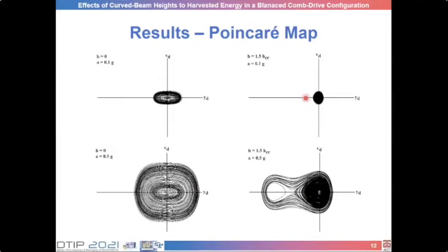When we compare these two, we can see that in the straight beam case, there is more displacement because of the lower spring constant. At lower acceleration, the displacement is around the original stable position. In the higher acceleration case, we can clearly see the snapping between two bistable positions.